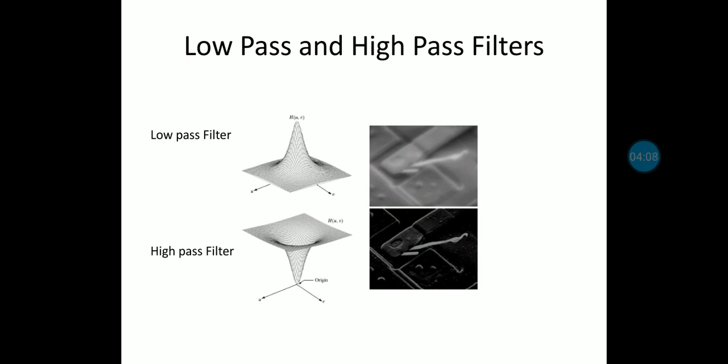Once it is passed through a low pass filter, the blurriness has been increased in the original figure. When we pass it through a high pass filter, we are able to see a dark image, and one more characteristic we observe here is that the edges of the damaged IC are seen very clearly. So low pass filtering normally contributes to the smoothing operation, and high pass filtering contributes to the sharpening aspects of an image.